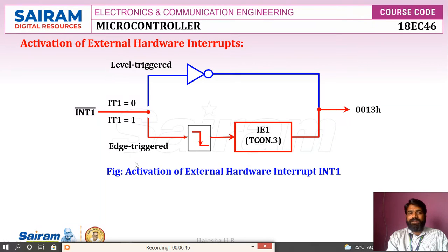Similarly for IT1, same thing, but the only change is INT1, IT1, and IE1, and the address is 0013. This is 0003, this is 0013.